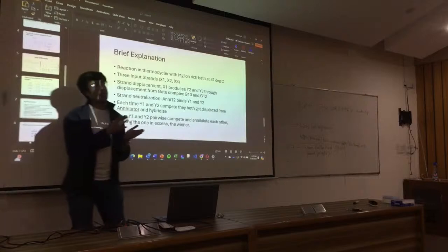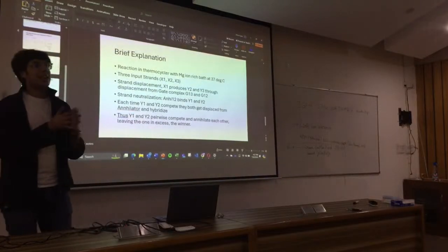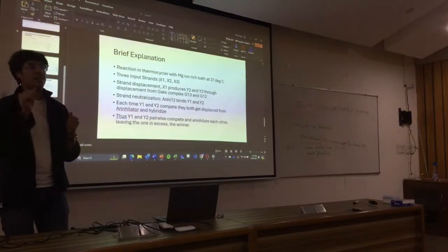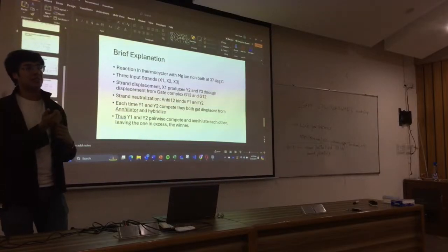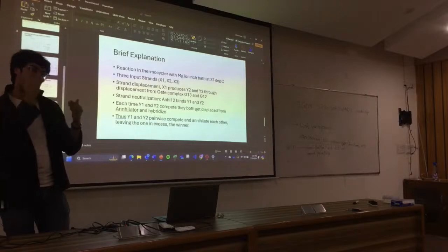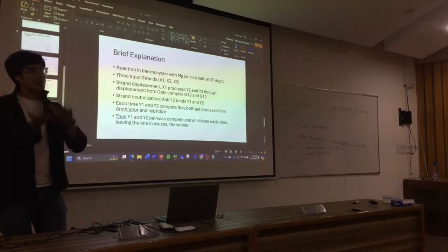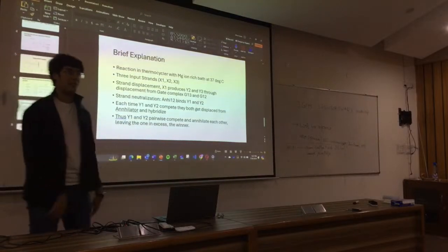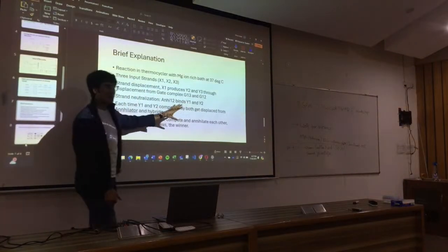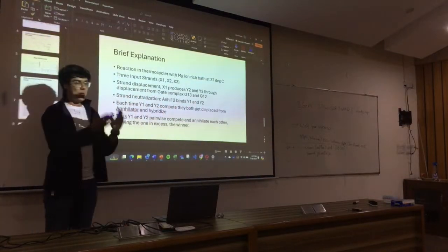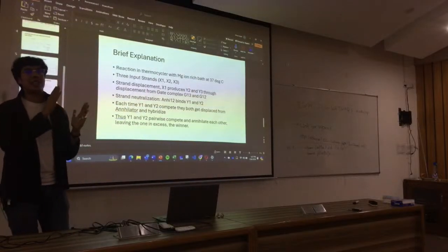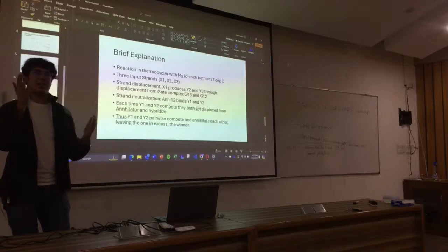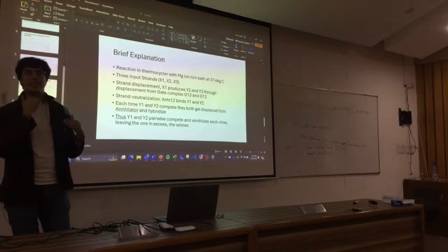This is the same as taking the average minus the input. You average the 3 things out and you subtract the same quantity from it, right? So you subtract it from the average, which means you reverse the inputs, input reversal. This is what the gate complexes do. Strand neutralization. So once you've got the reversed input, if X1 was the least, Y1 becomes the most. If X3 was the most, Y3 becomes the least.